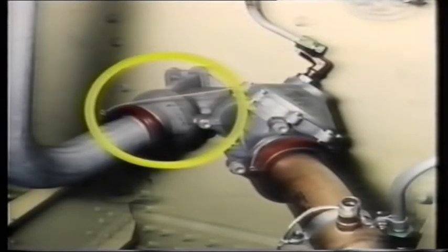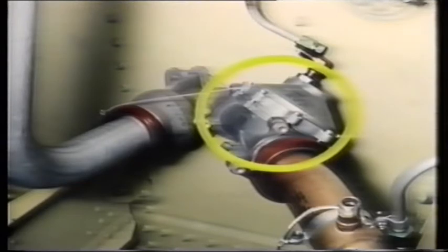Fuel pumped through a shrouded transfer line enters the center tank, then splits into 2 redundant lines, each containing an isolation valve, a primary refueling valve, and a secondary refueling valve. Fuel in the number 2 and 3 reserve tanks transfers by gravity to the inboard main tanks. It passes through the 2 reserve transfer valves for each reserve tank.